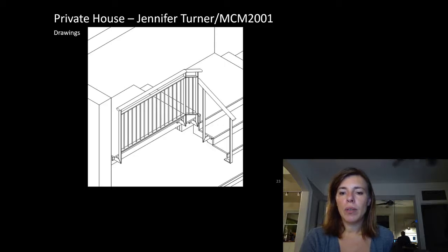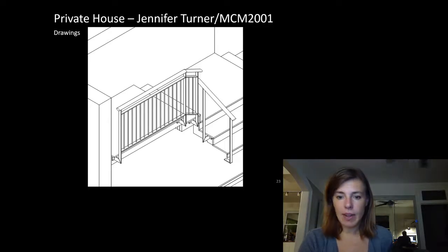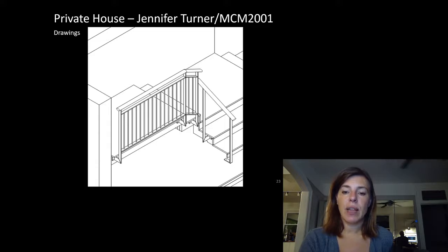So it's really important to know what material you're modeling with. In steel, it's important to know whether it's stainless steel or not, because stainless steel is not as strong as regular structural steel. Whenever we've talked about steel in the past, we've been talking about structural steel. Stainless can definitely be structural, but it's a different grade of material, and you have to know which stainless steel they're using, and it has a different strength capacity.